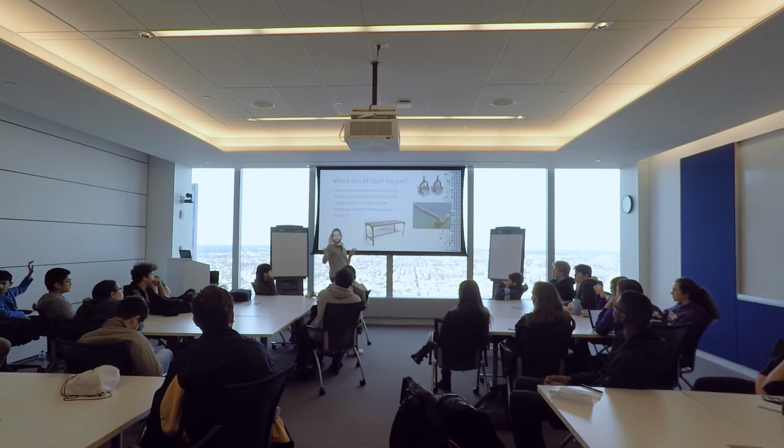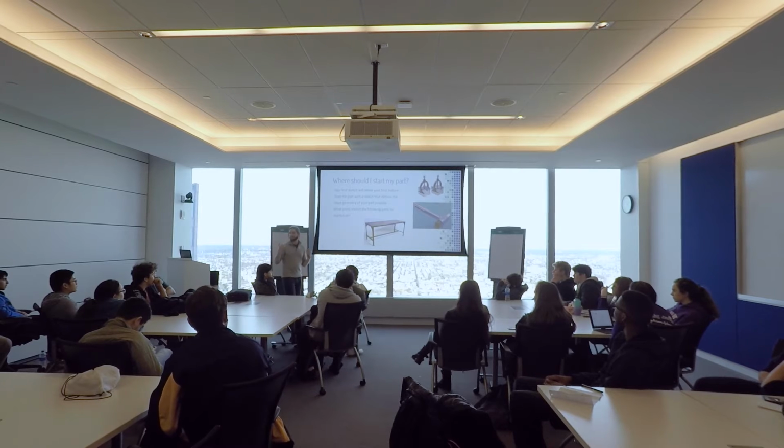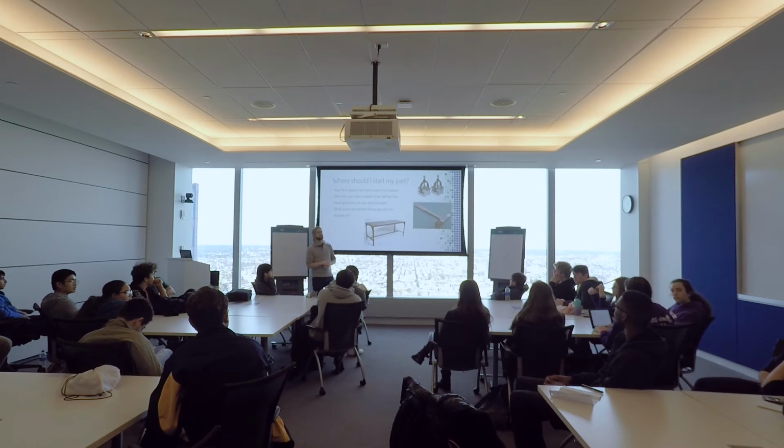Yeah. Okay. I would suggest that you make your top plane the bottom of the table, actually. It's kind of counterintuitive, but for almost everything that I model, including at work, the floor is the top plane. Again, a little bit counterintuitive in terms of the naming, but I would do that. But I wouldn't necessarily even start my sketch from there. I would start my sketch from somewhere else. I'll sketch one of the sides and then extrude out and then just cut the axis. That's an option too. Do you guys know about beam tools?